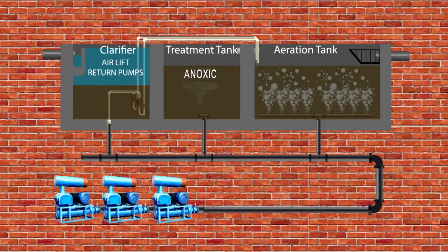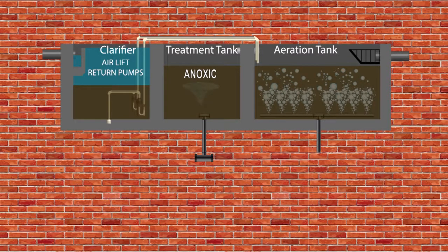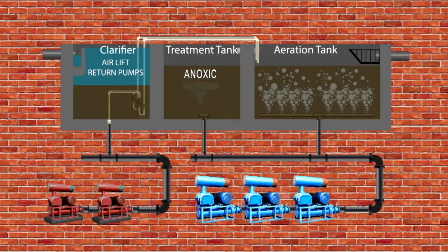The site had 3 10-horsepower blowers, along with 2 smaller blowers, all of which were connected to a common air header. We weren't sure if the smaller blowers were intended to be used in cold weather or what their intended purpose was. The smaller blowers were separated from the common header and used for the airlift sludge return pumps only. Our thought was to use the aeration tank to provide most of our treatment and then use the existing anoxic tank as a polished denitrification stage.